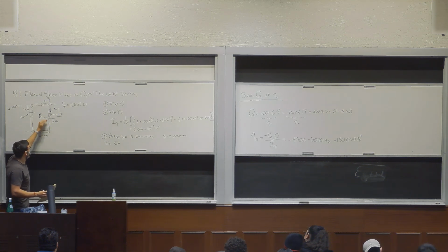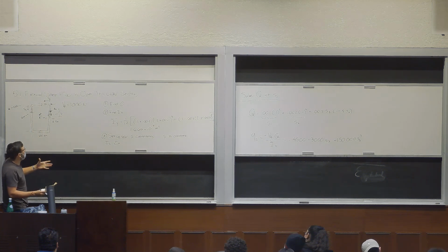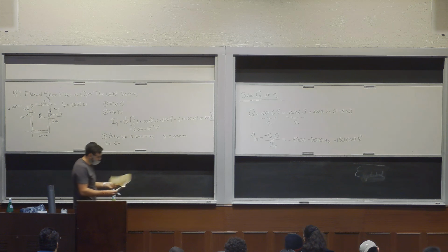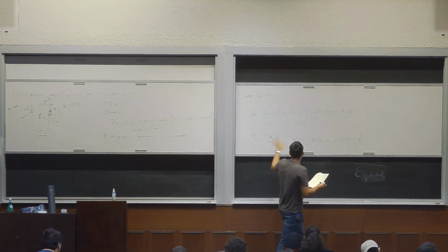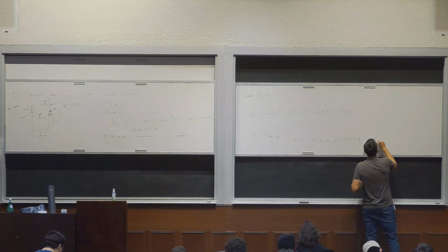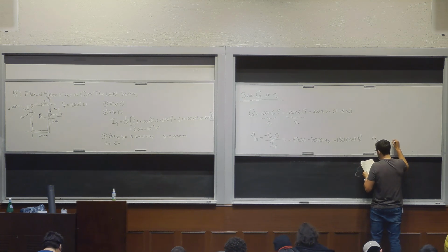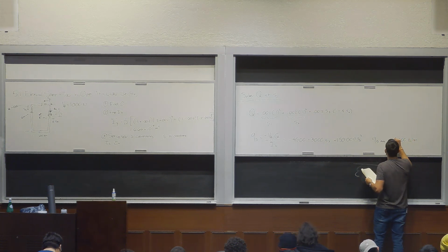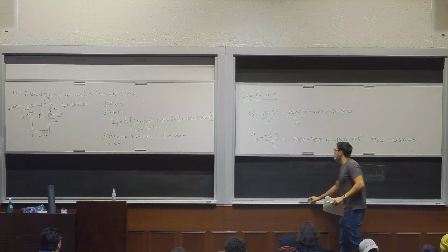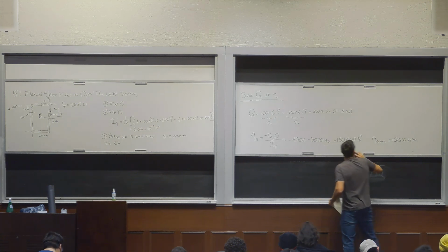So you could start S4 here, solve for Q, solve for shear flow, then add this one. And you'll find that for this problem, since it's symmetric about the y axis, the distribution is basically mirrored. Okay, so now let's draw what that distribution is. Oh, I forgot. If we find the max of this, so Q S max for that third portion equals 6,000 newtons per meter, negative. So you guys know what that means. And now we're drawing the distribution of this.